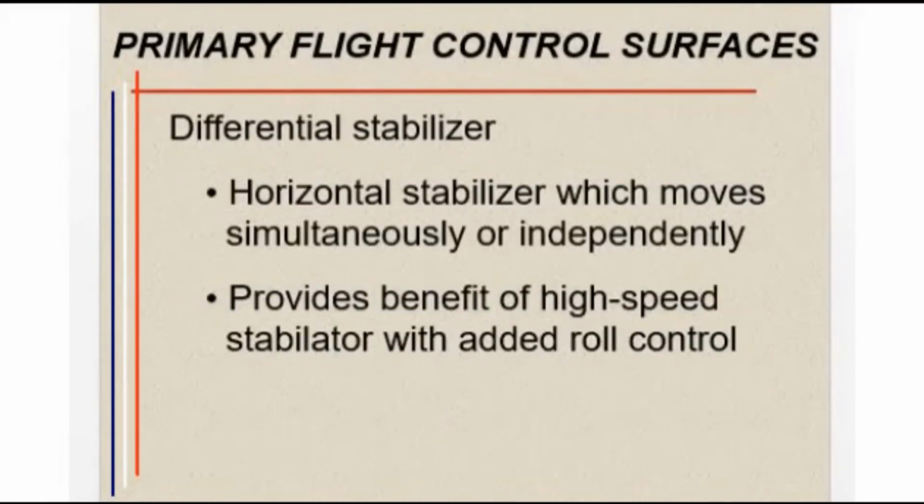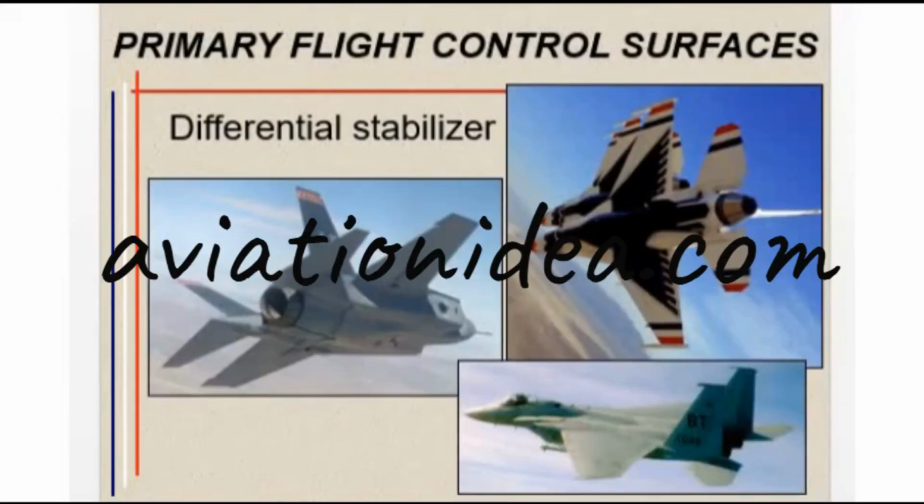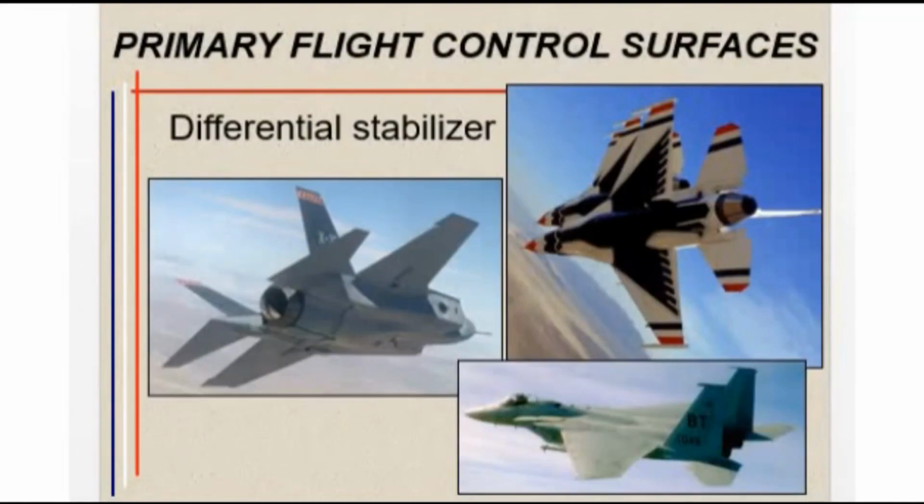Differential stabilizers of an aircraft are used on high-speed aircraft such as the F-15, F-16, and B-1, see figures 15 and 16. A differential stabilizer acts as a stabilator to control the pitch of the aircraft. However, each side is also able to move independently of the other. This allows the stabs to assist ailerons with roll control. This is significant at high speeds where it provides flight control functions normally handled by the controls on the wings, and allows us to further combine flight controls on the wings for weight reduction, see flaperons below.